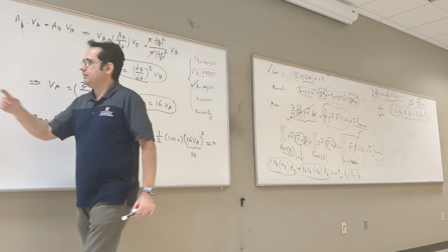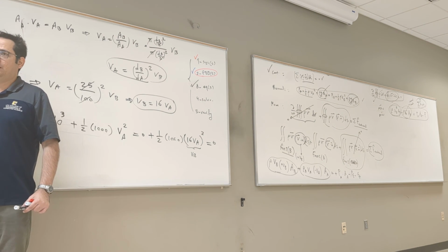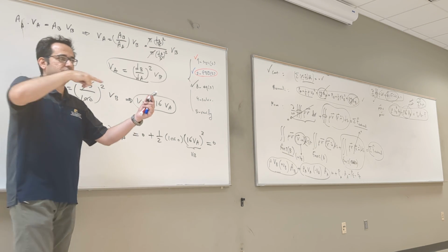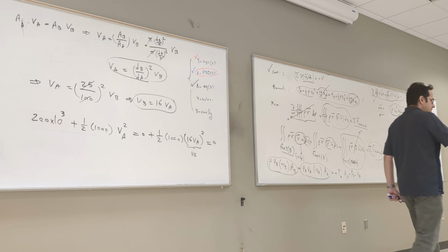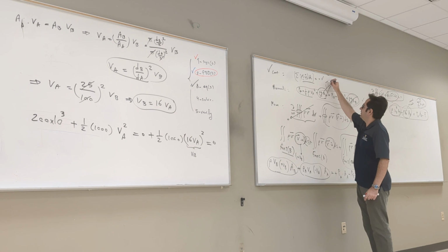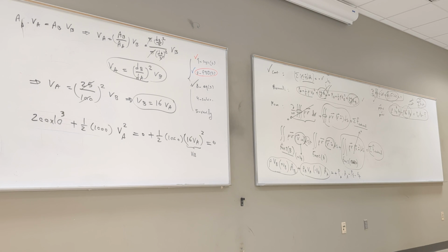In other words, if you consider just inside this, from A to B in a straight line, you don't see the wall. It's almost frictionless, but the real thing is not frictionless. In the real thing you have friction, you have pressure drop. In the next chapter, when you do the energy equation, you subtract by plus or minus HL, and you get a more accurate result. You'll see that. But right now, let's say frictionless.